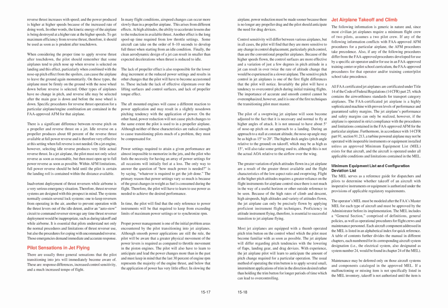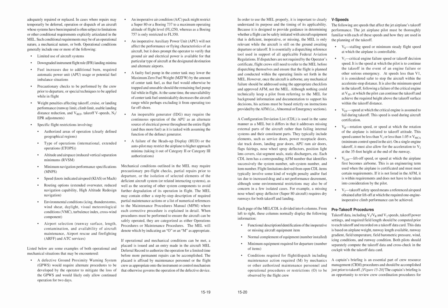Maintenance may be deferred only on those aircraft systems and components catalogued in the approved MEL. If a malfunctioning or missing item is not specifically listed in the MEL inventory, takeoff is not authorized until the item is adequately repaired or replaced. In cases where repairs may temporarily be deferred, operation or dispatch of an aircraft whose systems have been impaired is often subject to limitations or other conditional requirements explicitly articulated in the MEL. Such conditional requirements may be of an operational nature, a mechanical nature, or both.